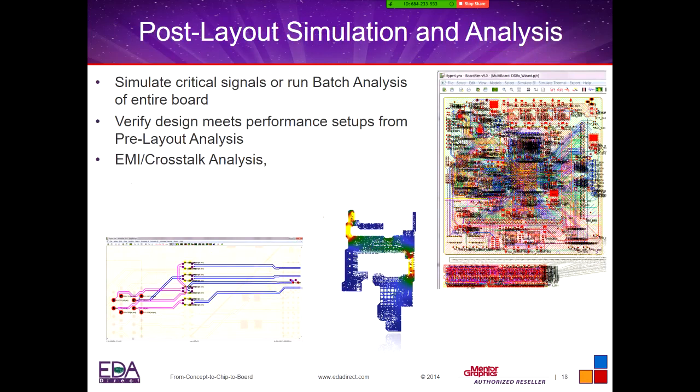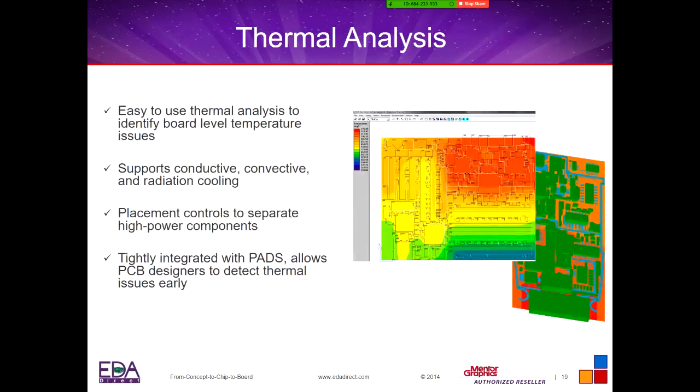Also, you're going to be able to do analysis after the board's been laid out. So maybe some of you send your designs out to service bureaus and you want to make sure that the signals are correct. Or maybe you have a clock line on there that you want to check. So you have full verification to check for EMI, crosstalk, impedance control, even after the board's been laid out. So there's your pre and post signal integrity tools, as well as thermal analysis.